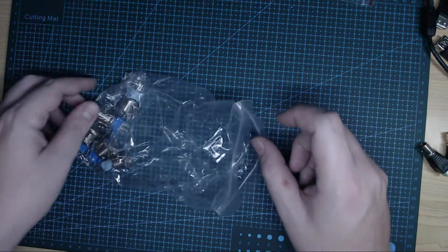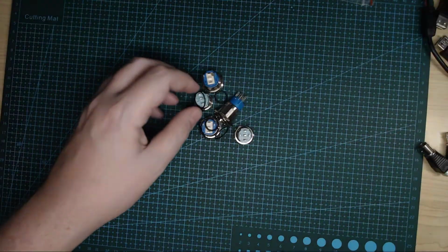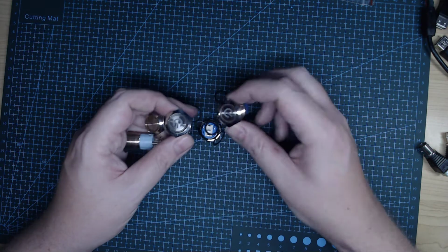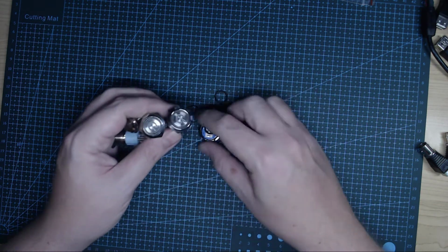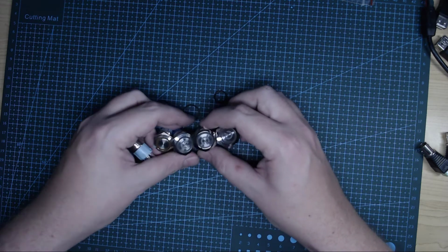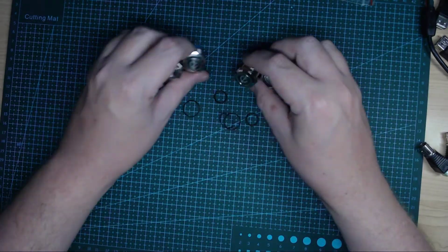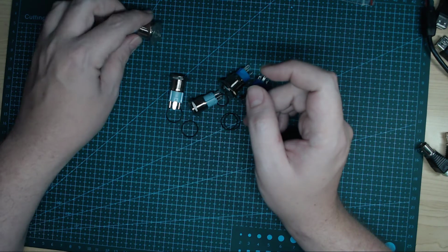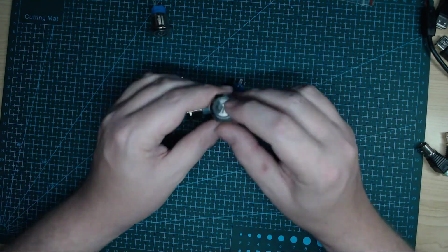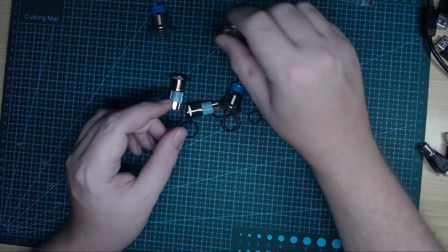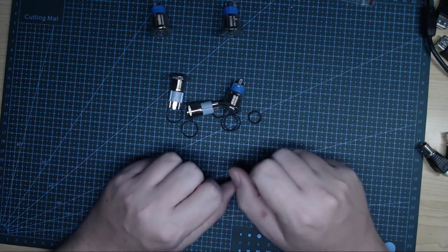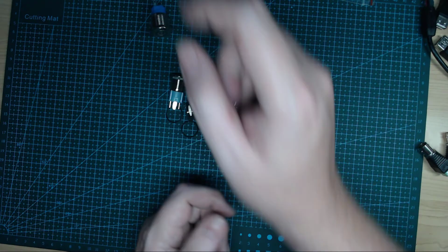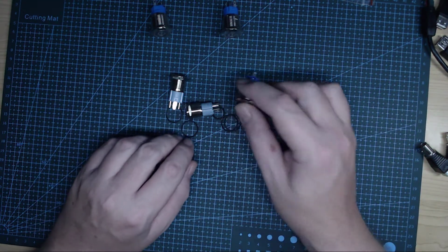Aha, I've been waiting for these for a long time. So these are illuminated power switches and switches. So this is for the power supply project. I figure I'm going to have sort of a switch on, switch off for mains power input, switch on, switch off for the battery power input. There will also be a selector rocker switch on each of the two power supplies to select whether they're coming from mains or battery, but so I can hard kill the mains power supply to make sure there won't be any accidents or whatever such.